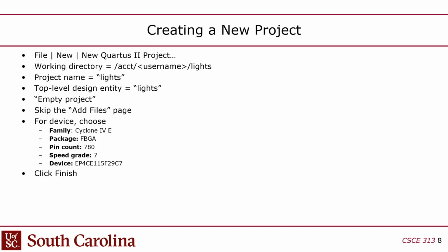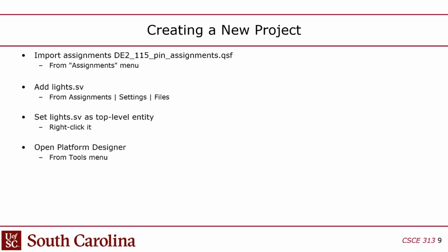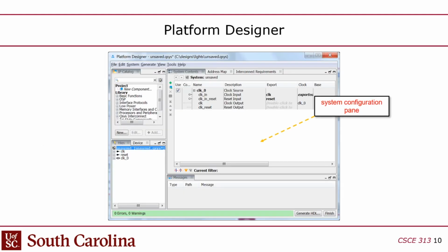And I'll give a demo of this next lecture. You import assignments, so you import the pin assignments. That file is available on Dropbox. And then you have to add a SystemVerilog file. We just call it lights as an example because it's one of the blinking lights tutorials.